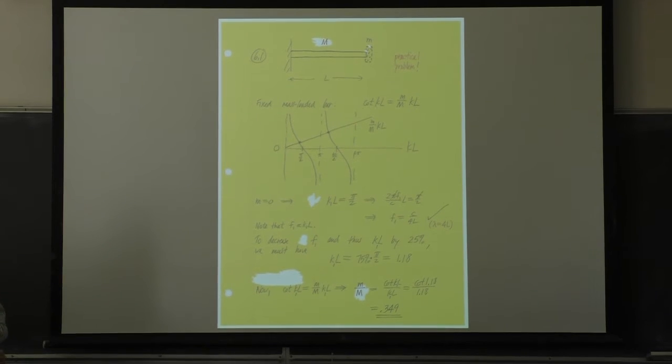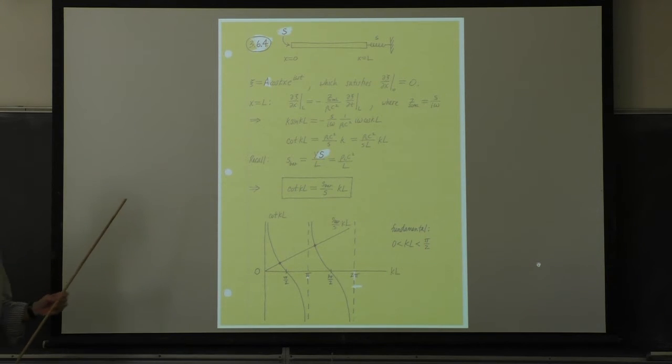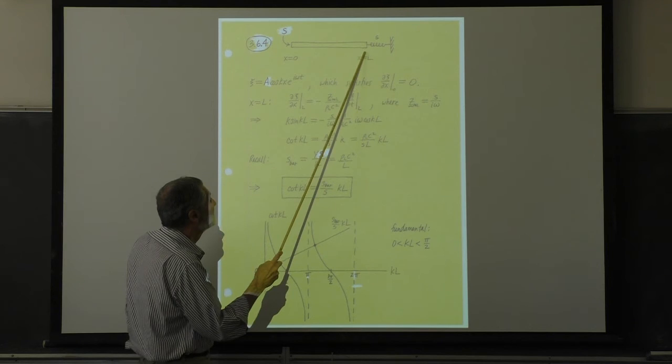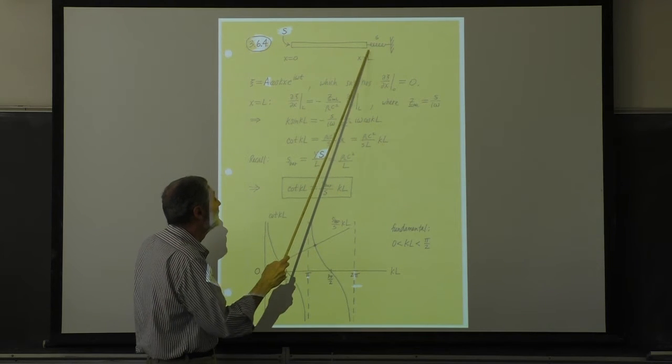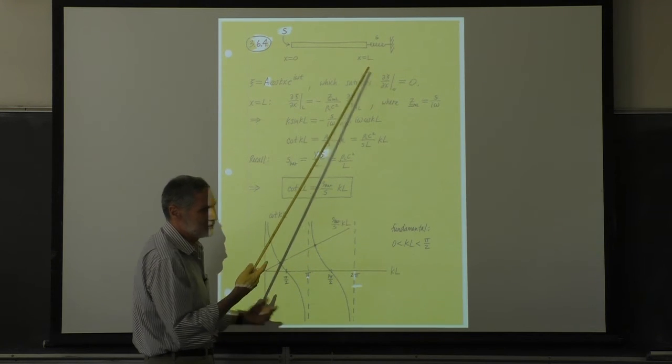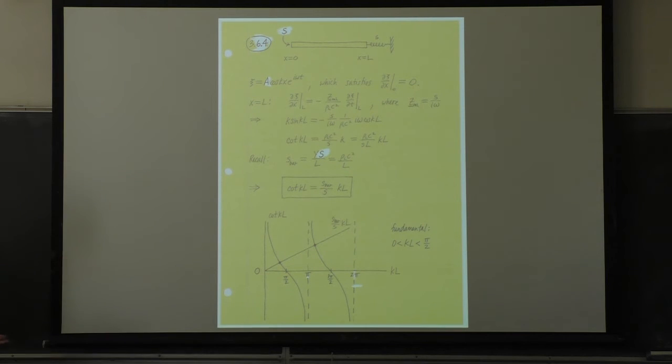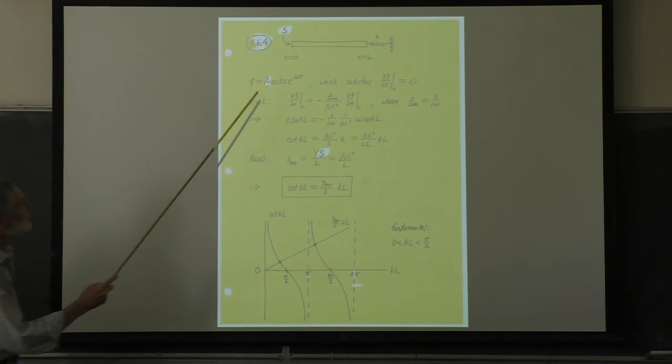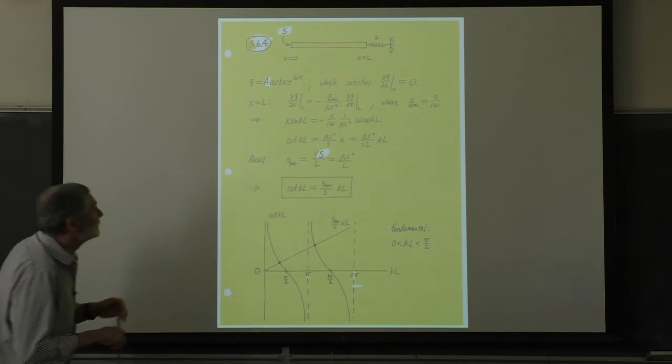Okay, so the next problem is 3.64. Determine the expression giving the fundamental frequency of longitudinal vibrations of a fixed-free bar of length L, if the free end is terminated by a reactive impedance. Okay, so it's not that free, is it? So here's how we would draw it. They're giving us a reactive terminating impedance here, which is spring-like. You notice the impedance is like an inductor. So this is the problem we want to do here.